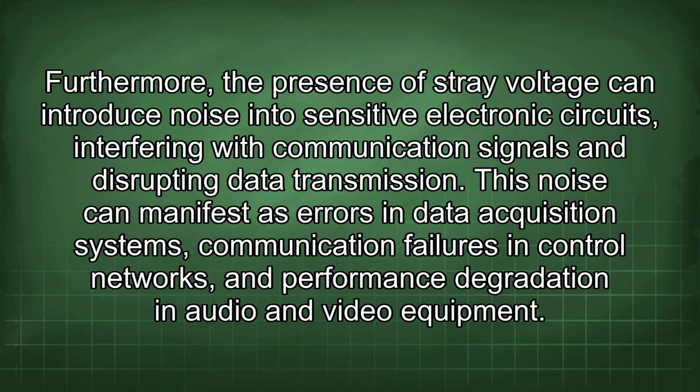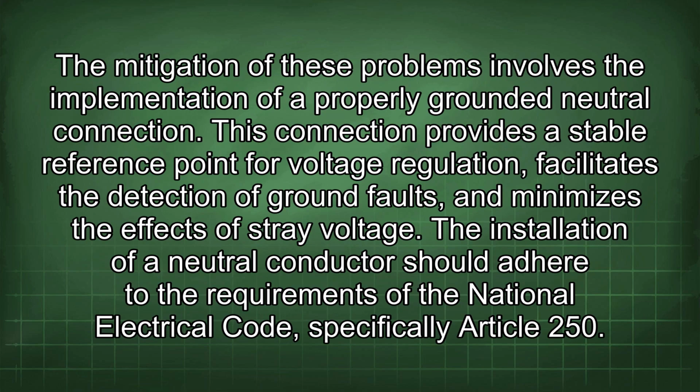Furthermore, the presence of stray voltage can introduce noise into sensitive electronic circuits, interfering with communication signals and disrupting data transmission. This noise can manifest as errors in data acquisition systems, communication failures in control networks, and performance degradation in audio and video equipment. The mitigation of these problems involves the implementation of a properly grounded neutral connection.